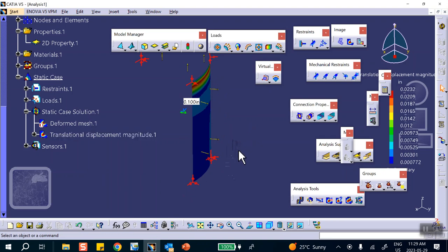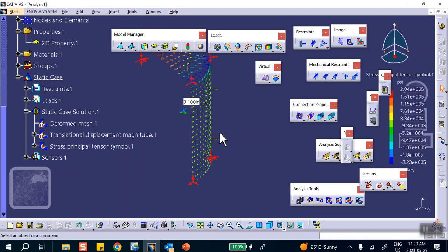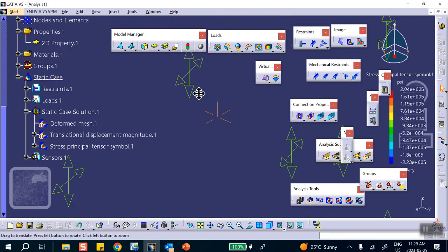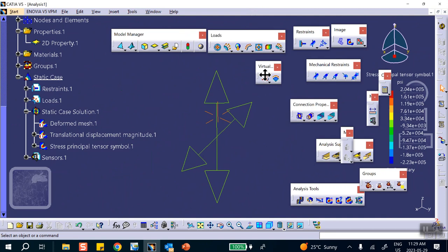All right. Now, one last thing I want to show you here is the principal stresses. So not von Mises, but see over here, expand them. The second icon, principal stresses. And if you zoom in, you see they're both tensile, and I bet axial one is half of that.